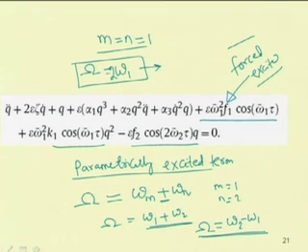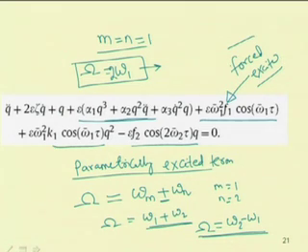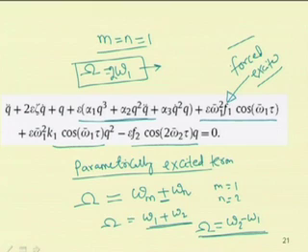But in case of parametrically excited system, you can have two different types, one is principal parametric and the other is combination parametric. But when you are adding the nonlinear terms again, the resonance may occur at a frequency which may be away from the natural frequencies also. So, you may have sub-resonant or subharmonic or superharmonic resonance conditions. So, now you know 4 different types of resonance conditions: subharmonic resonance condition, superharmonic resonance condition, principal parametric resonance condition and combination parametric resonance condition. In addition to the resonance which occurs at a frequency equal to the natural frequency, that is known as simple resonance condition. So, 5 different types of resonance condition you may observe in case of a nonlinear system, but in case of a linear system you can observe only the resonance when the excitation frequency equal to the natural frequency of the system.